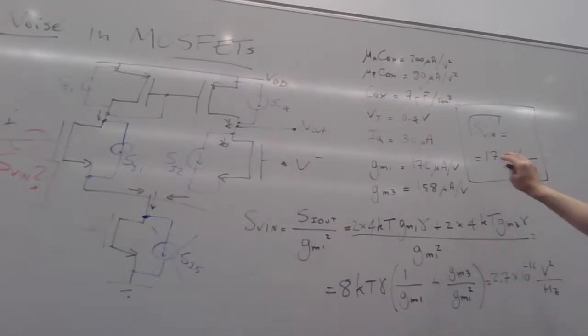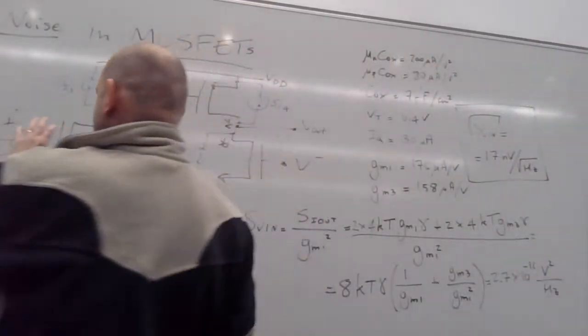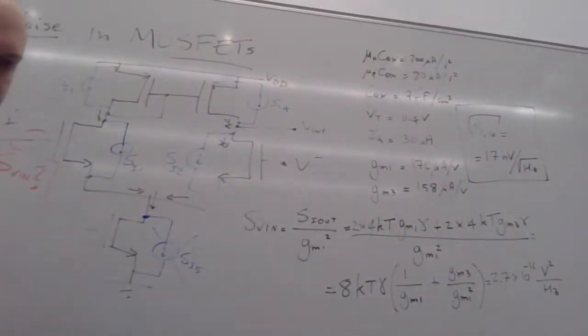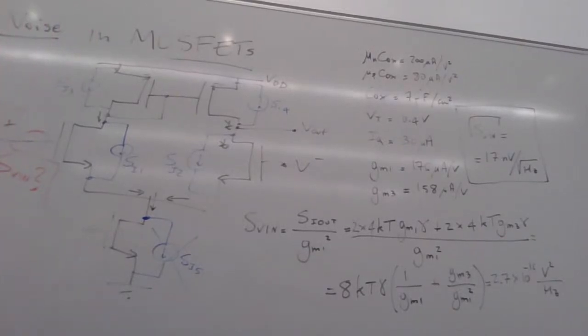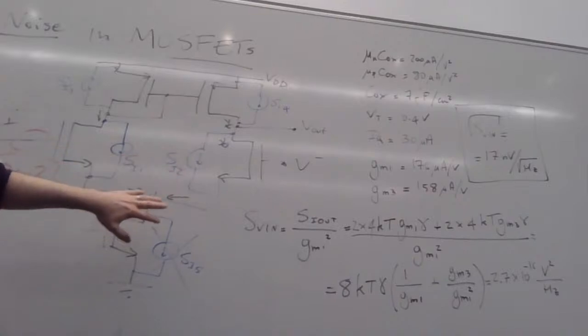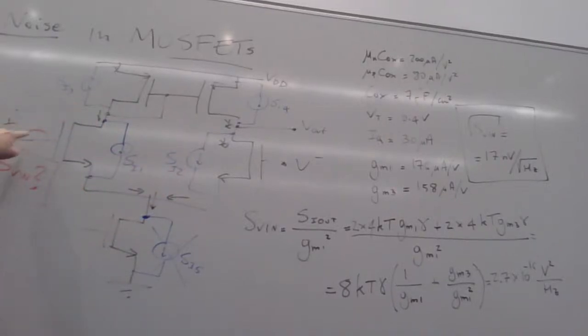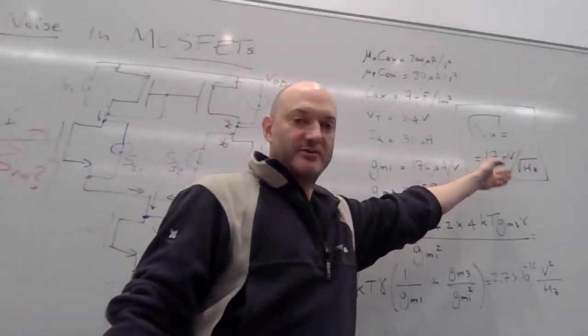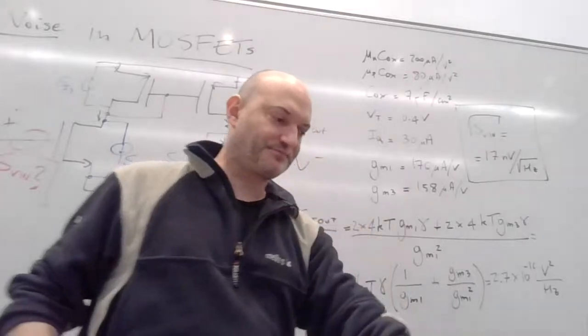Right, so finally we got our final result, and this one is what goes to the equivalent noise source, so you don't worry about all the contributions of the individual MOSFETs. All you care is that is equivalent noise source, and you know how to calculate the value. Okay.